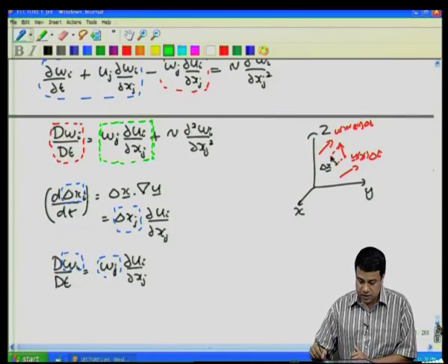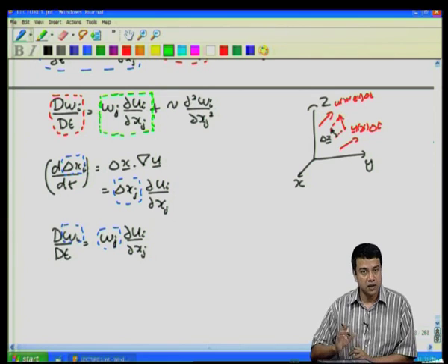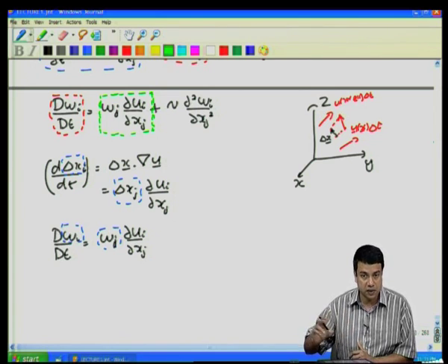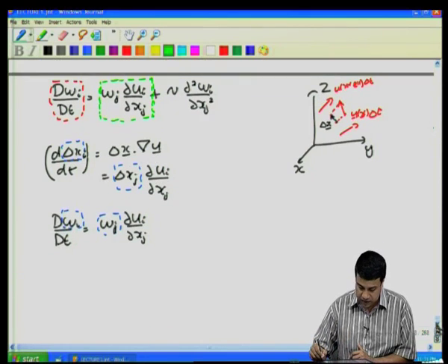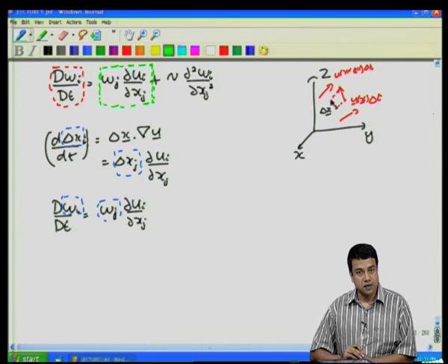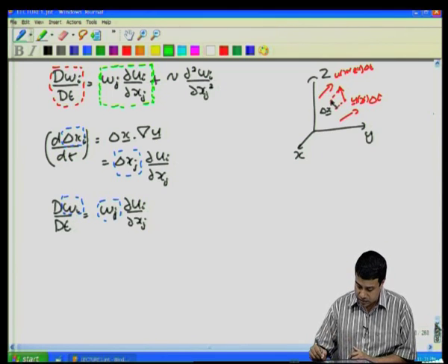So, this is the additional element. Unlike momentum, vorticity is not a conserved quantity. Vorticity could be created or destroyed in a flow, and the rate of creation or destruction is proportional to the rate at which material elements are expanding in the flow. This rate is also proportional to just the symmetric part of the rate of deformation tensor. So, let us just look at this.